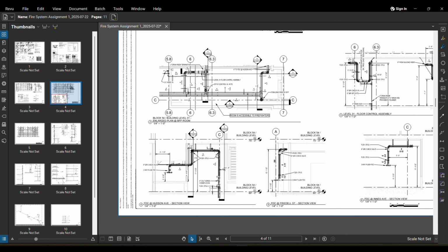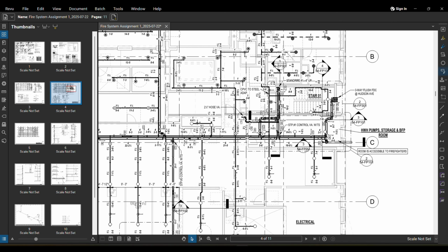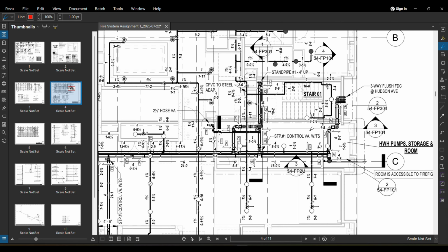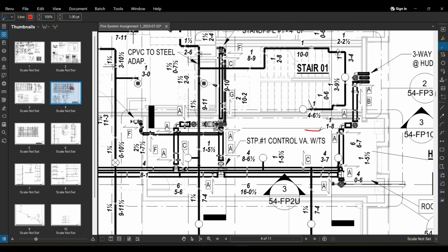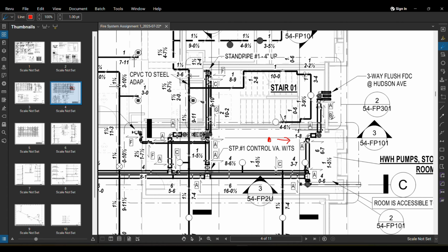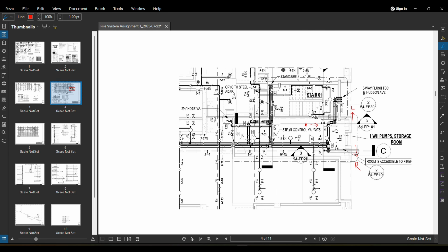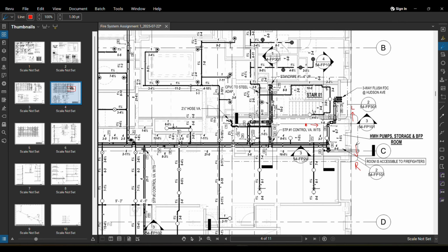Can you see? How do we read this particular section? We'll just see the direction of the section. I'll take a pen and draw an arrow here. On this particular section, we are viewing from this angle, from this arrow. We're standing here and viewing in this direction, and everything on this side should be on the left, and everything we see downwards of this section should be on the right. So everything on the left should be this, and everything on the right should be this.